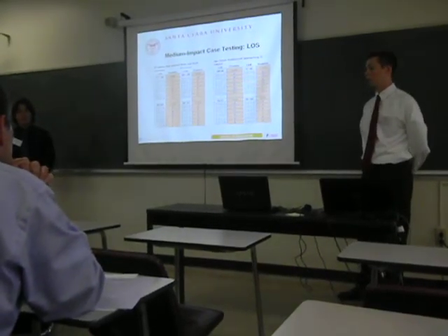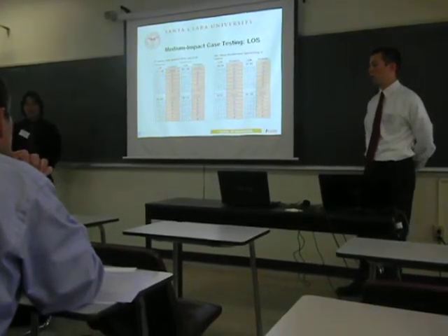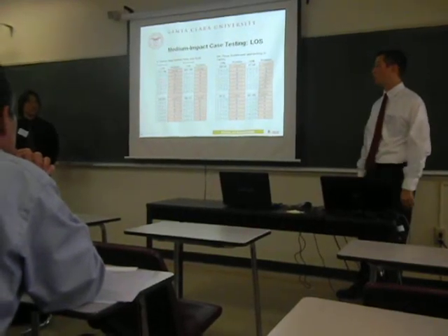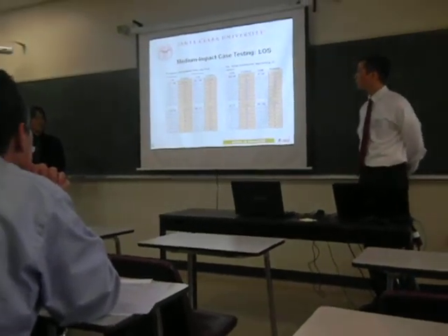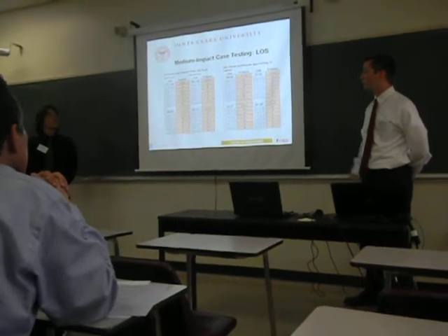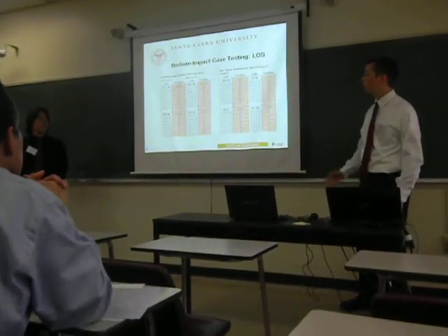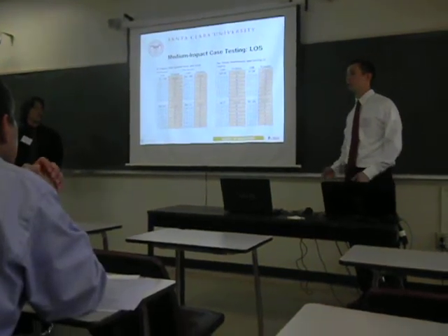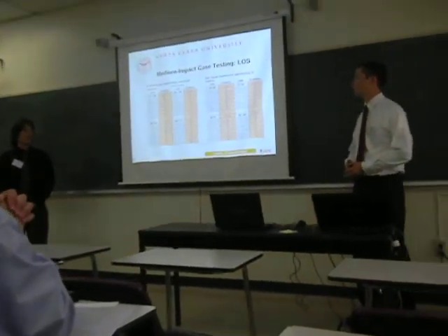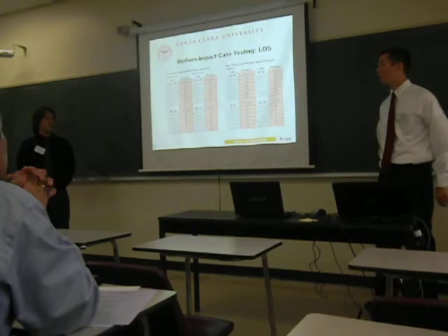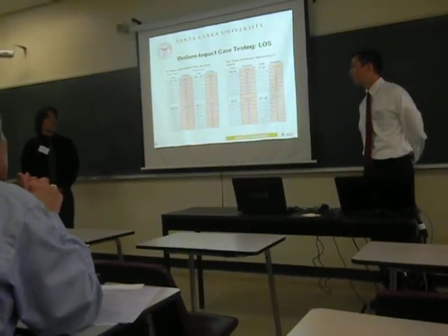We also ran level of service testing for different corridors surrounding the blocked off street. Here you can see LOS testing. The program takes it at 5-minute intervals. We ran LOS testing for El Camino between Kylie and Scott, as well as Santa Clara southbound approaching the closed off road.